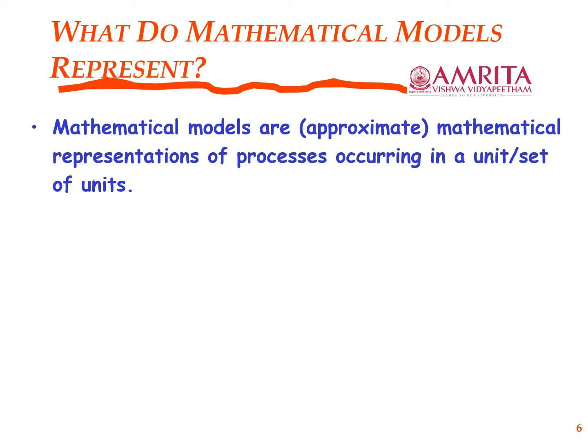So essentially, the flow of the vapor up the column, the flow of the liquid down the column, the equimolar or non-equimolar counter diffusion that takes place between the vapor and the liquid phases in each stage, and then there may be some sort of a stream coming in due to a pump around, or going out or coming in due to a side stripper, and the various product streams that are exited at different stages. There is a feed that comes in at a feed stage. All these are processes that take place, number one.